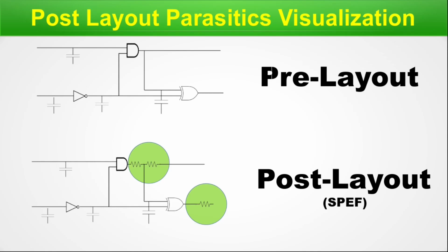Another avatar of the SPEF file is SBPF, which is a binary file and hence cannot be read by human beings. This is for the STA tool consumption only. For very large designs, SBPF is useful because of its faster loading time. Now, one thing I would like to say before concluding, this annotation is done by some of the EDA tools. The SPEF file contains the information of these additional parasitic RCs. Those are highlighted in this diagram. So we are done with this particular slide. So let's move on.